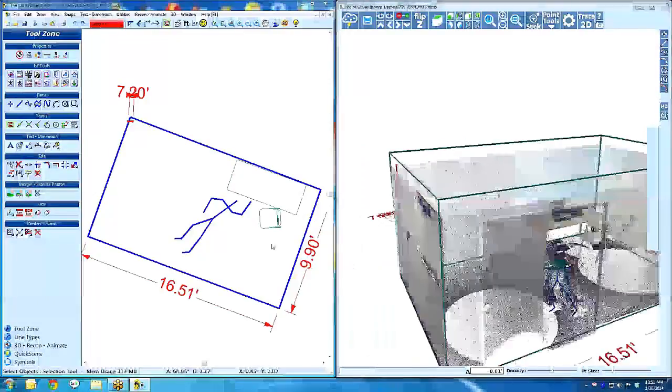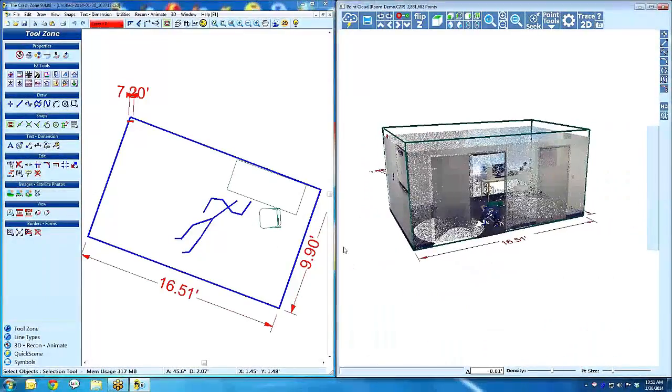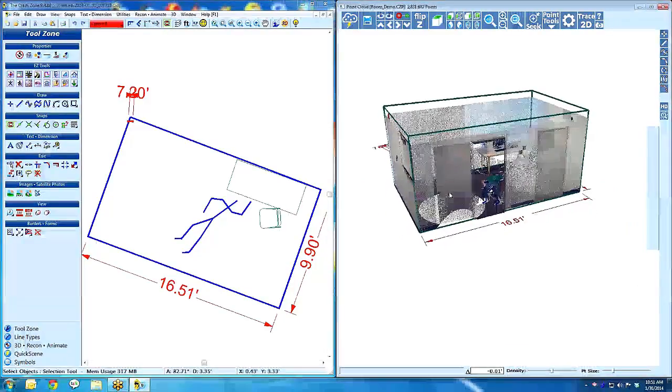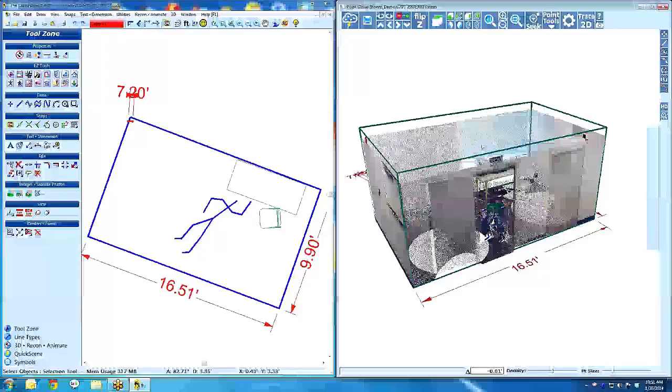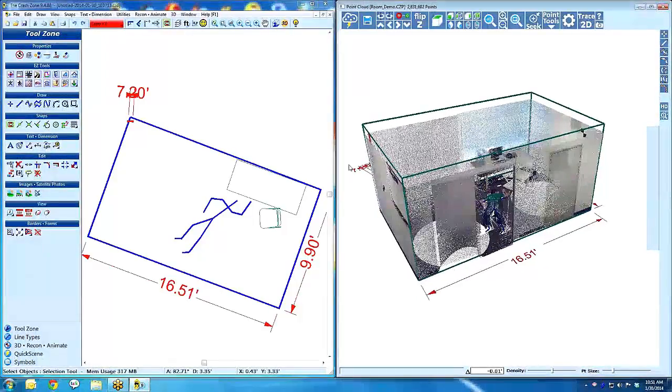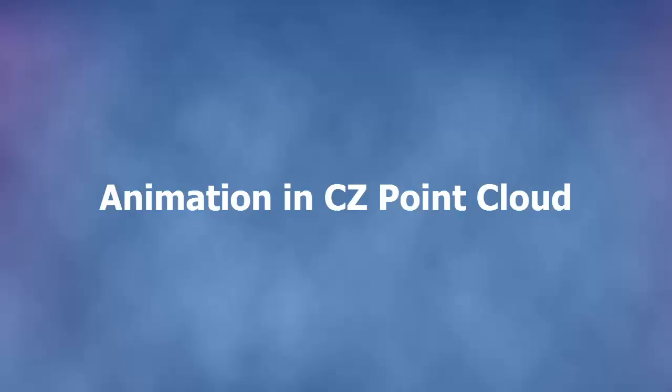So you can turn off this point cloud and work on this as a drawing. I mean, remember, it's just the total station on steroids. You're getting all these millions of points. You're creating your drawing, picking what you want, and you can finish your drawing up. You could shut this off, but you could come back a week later and open that cloud up again if you forgot something and add more to it.